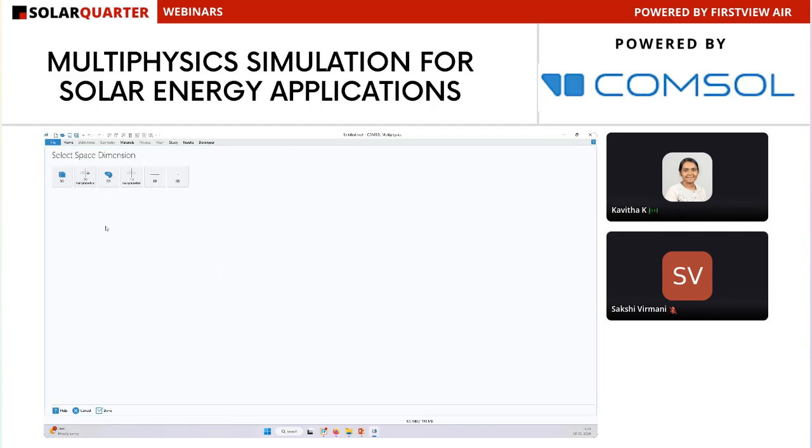And once you choose the model wizard, you will get a screen where you can select the space dimension, whether you want to model in 3D or in 2D, or if you are going to have axisymmetry in your model, then you can choose 2D axisymmetric. So in our example, we are going to model in 3D. So let me choose 3D. You can ignore the recently used. Here you will be listed with the different physics that are available. It will depend upon the modules that you have installed on your computer.